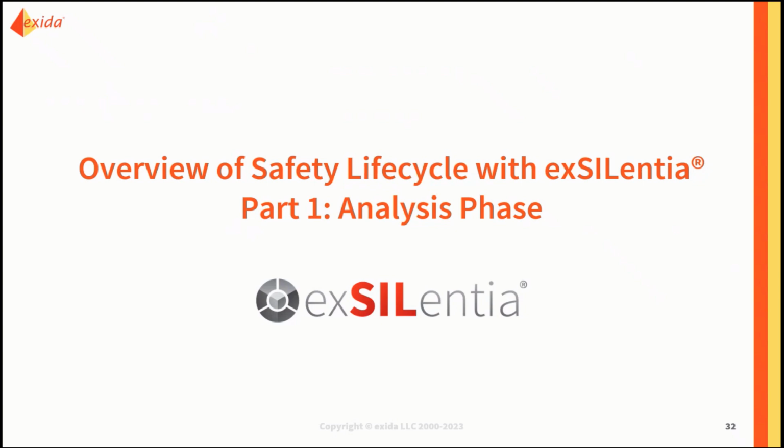We are going to have a part 2 that addresses the design phase and the operation and maintenance phase. So please attend that as well if you want to see exactly how you would model your SIFs in SILver, how you would consider cost, lifecycle cost. You want to optimize according to cost as well as reach your integrity requirements, how you would document the design SRS, and how you would move forward to do proof testing that is going to help to validate the assumptions you made in SILver and collect data over the life of your safety instrumented system.